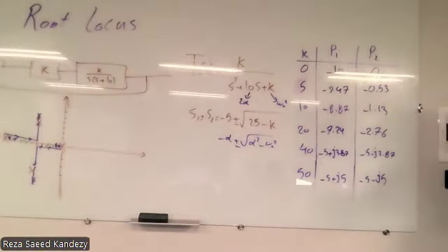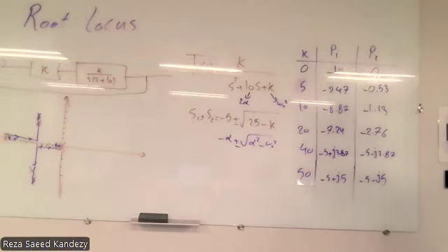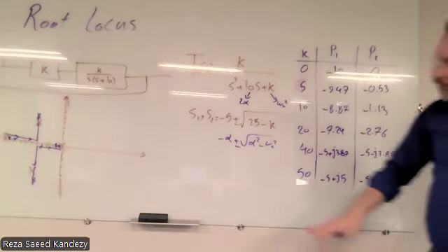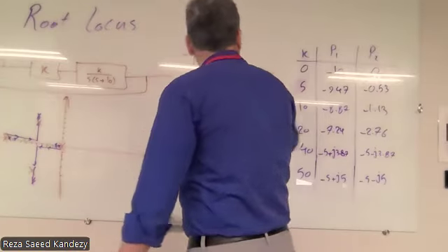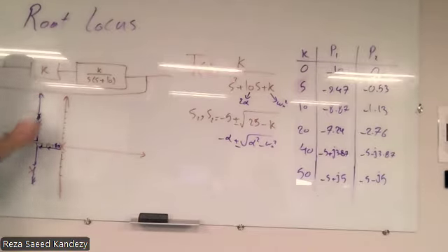Now, using your understanding of the stability that we talked about for a static system. If I have this system, which is this one, and I have a dynamic parameter, which is that K, okay? By changing that K from zero all the way to infinity, we can see that if I increase the K, the first pole is moving up, the second pole moving down.